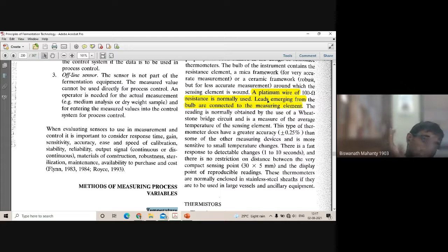So we have to do a calibration outside. What does it mean? We take the same device, put it in a fermenter, and change the temperature, for example. And I know if I change the temperature to 40 degrees, I get this much of a voltage difference across the wire ends. So I will note down: this is the temperature, this is the voltage change. Basically, every instrument and every instrumentation panel is to be calibrated before we use it. But by principle, we can have these kinds of approaches for temperature measurement.